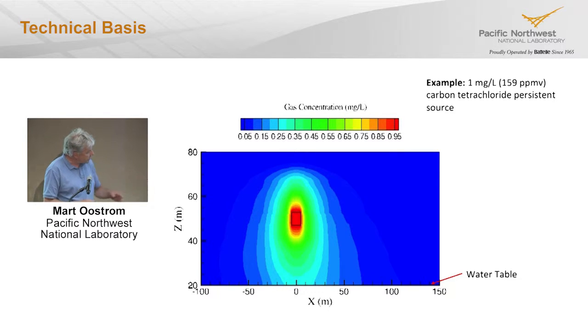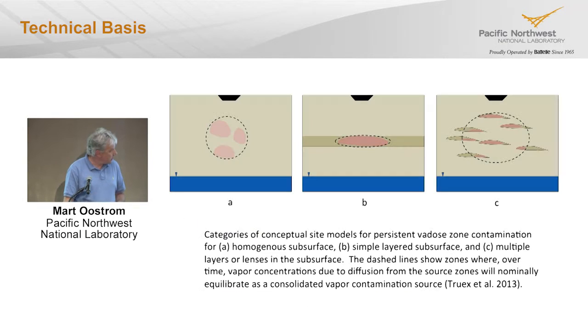What you also see in this picture is that the whole gas phase plume is shifted somewhat towards the right. That of course is related to how the contamination is partitioning to the groundwater. But when you look at this picture, like maybe remember from the previous slide, you have a low permeability zone in the center. The effect of the low permeability zone is hardly visible in these kinds of systems, and I'll go into that a little bit later.